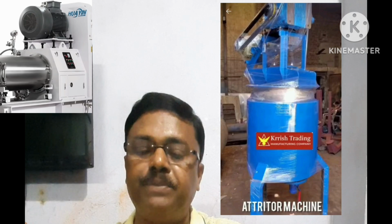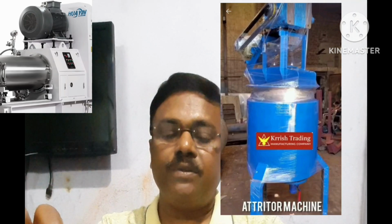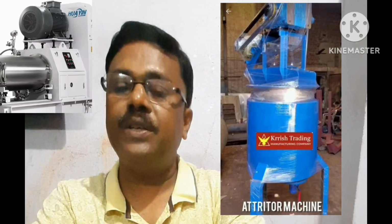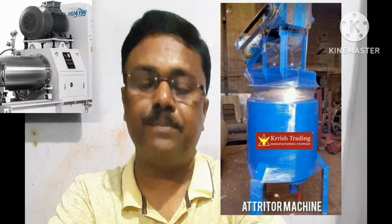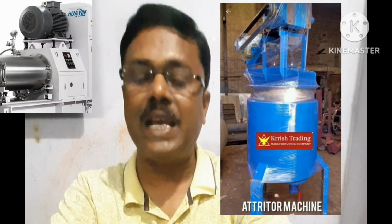About 50% of critical speed is required for rotating the ball mill. If a 6 feet diameter ball mill is rotated much faster than 16 to 19 rpm, then centrifugal force throws the charge against the inside periphery, where it becomes immobilized and dispersion cannot be obtained.